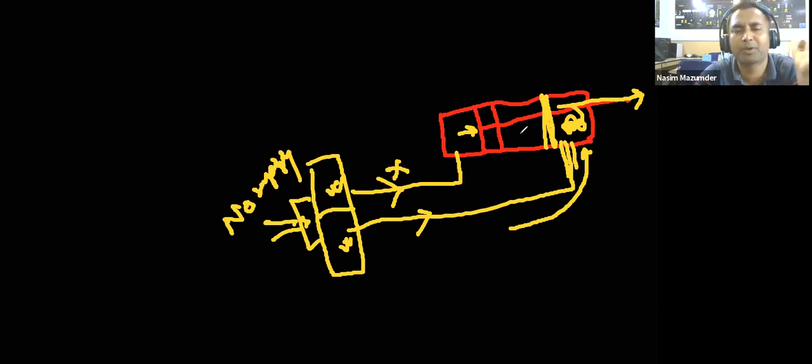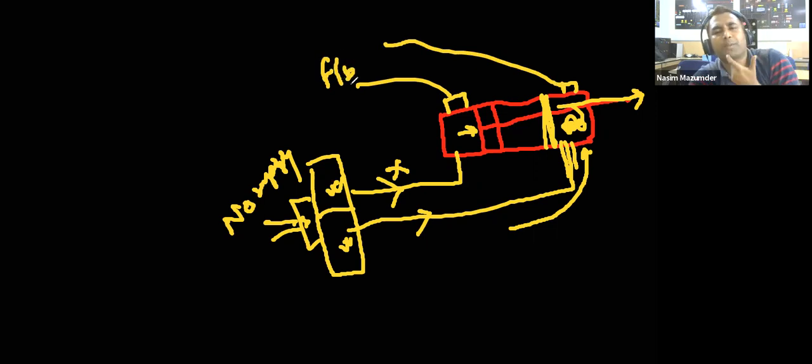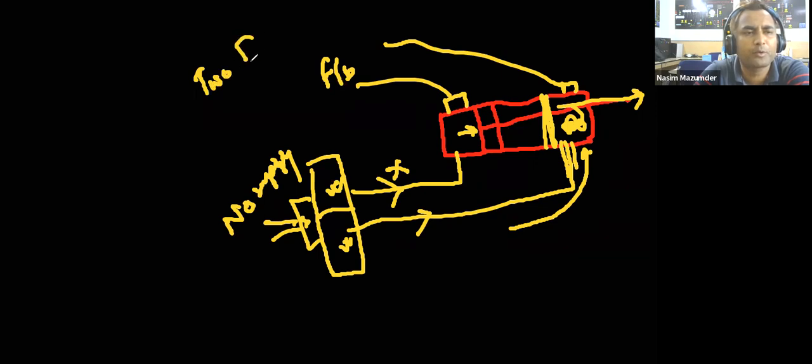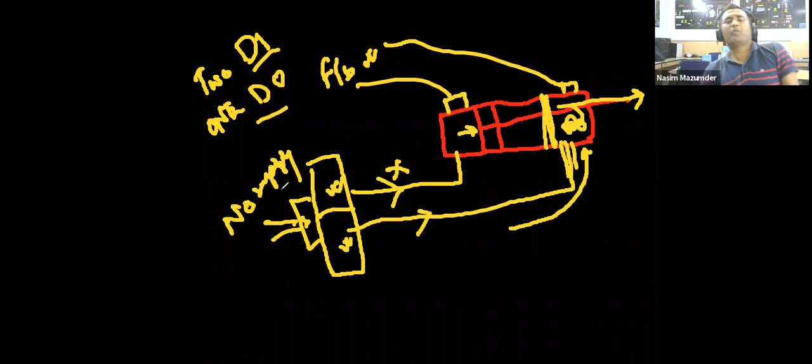So your damper will be closed, and there will be two reed switches connected to your PLC to give you the feedback. For a power cylinder, we need two digital inputs and one digital output. So if you are going to connect a power cylinder, you need three channels: two digital input and one digital output.